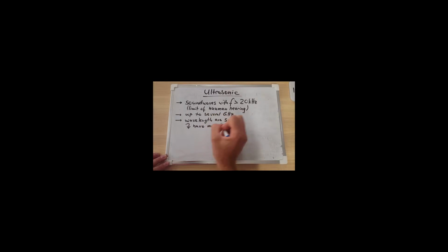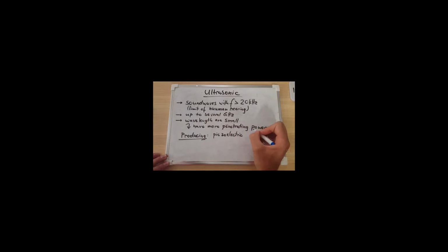These short waves have more penetrating power due to their shorter wavelength. They are produced by, for example, a piezoelectric oscillator. If an alternating voltage is applied to one pair of opposite faces of the crystal, alternating mechanical contractions and expansions are produced in the crystal and the crystal starts vibrating with the previously set frequency.